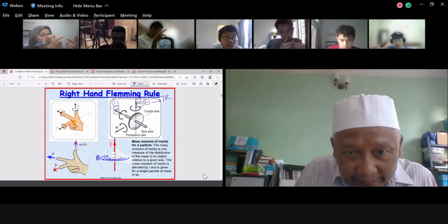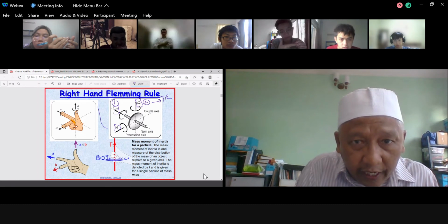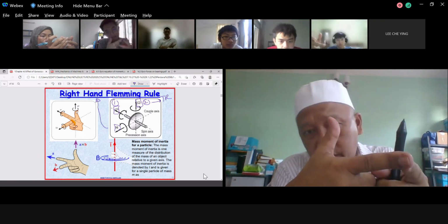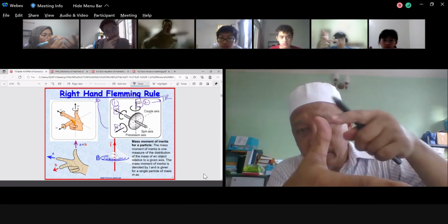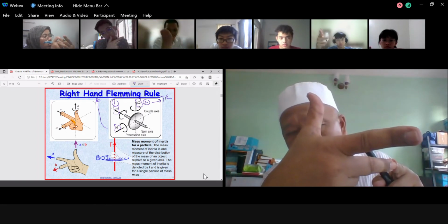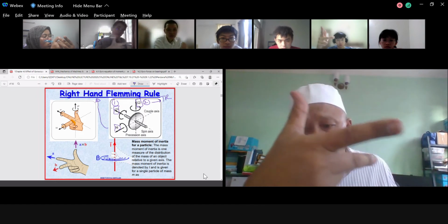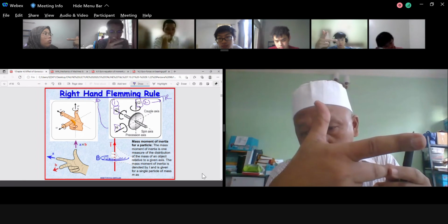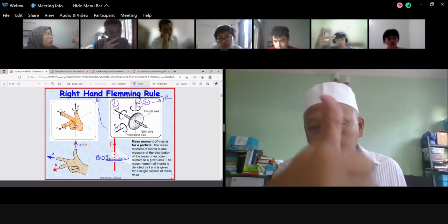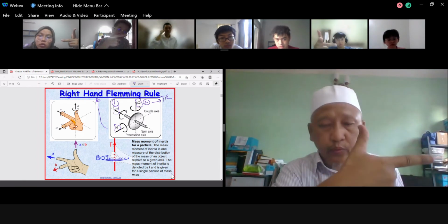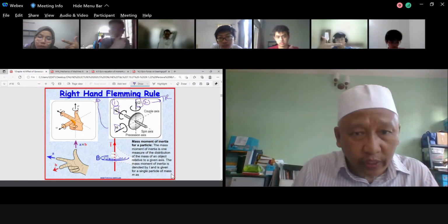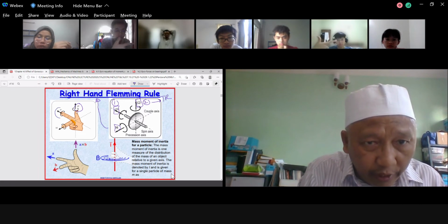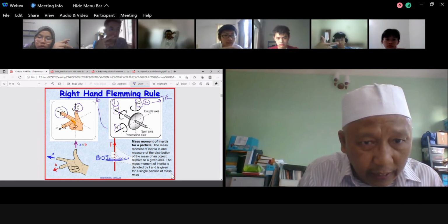Then to define this one is by using the right hand Fleming rule. How is it? Put your finger on the screen now. This is spin. This is precession. This one will be the couple. The couple will be pointing outward of your screen. Of course, if you see my video, my video is pointing the other way around, so it will be pointing inward. This one is pointing upward. This one is pointing to you. Correct or not? So then you know that this one is the pointer, this one is the thumb, and this one is the middle finger.